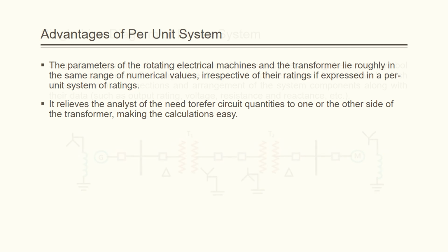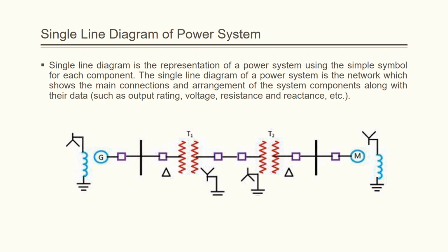Even though the per unit system has certain advantages, the major drawback is that some equations that hold in the unscaled case are modified when scaled into per unit. The factors such as root 3 and 3 are removed or added by this method. The equivalent circuits of the components are modified, making them somewhat more abstract. Sometimes phase shifts clearly present in the unscaled circuit vanish in the per unit system. So these are the major drawbacks in per unit system.